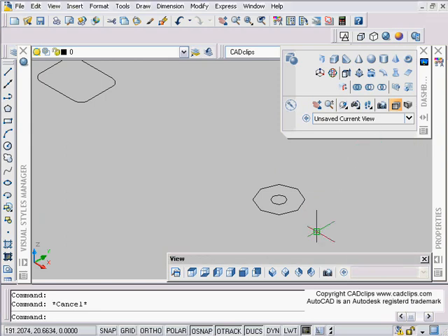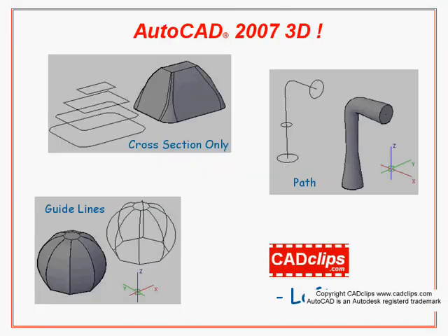What I'll actually do is skip back to my initial slide here and explain a little bit. With lofting with the cross section, all you have to do is provide lines that are closed, and in fact I don't even think they have to be closed, it'll close it for you, but you provide a series of lines that change elevation somehow and follow some sort of route. This is very uniform because I've tried to keep it simple, but with any sort of cross section, you provide the slices, and then it will loft the new solid over those objects. So I've kept it fairly straightforward.